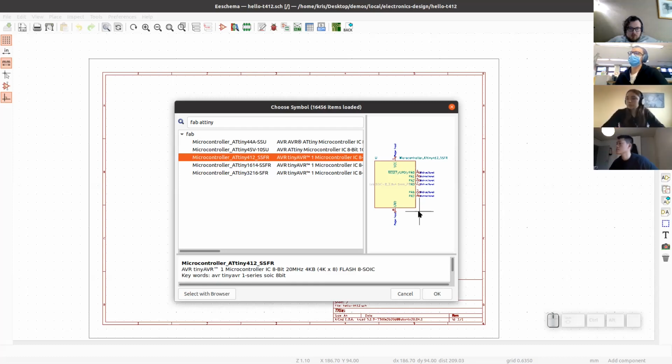And there's a whole KiCad convention that explains the best practices for how to design these symbols. Usually the rule of thumb is that you put positive voltages on the top, then negative voltages or grounds on the bottom, and then all the connections on the sides. If these are bidirectional or multidirectional connections, you can put them on one side or both sides, but then usually you would put inputs on the left side and outputs on the right side. But this is completely normal.